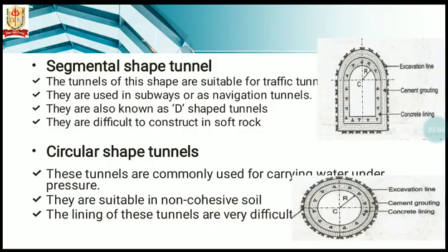Second type is the segmental shape tunnel. Tunnels of this shape are suitable for traffic tunnels. They are used in subways or as navigation tunnels. They are also known as D-shaped tunnels, and they are difficult to construct in soft rock.